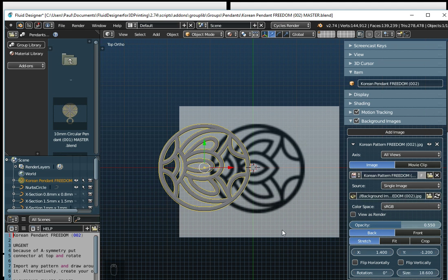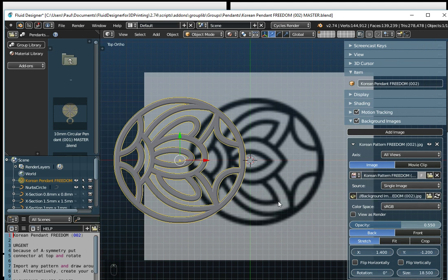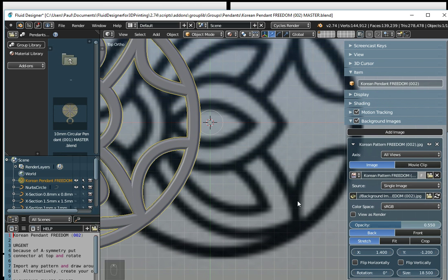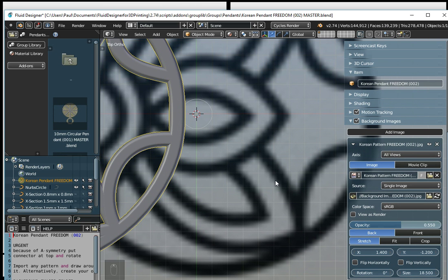And you'll have to play around with this, and essentially what I would suggest you do is select a size, put a path on here, and set the thickness to be 1:2 and see that it's okay. Alternatively, what you can do is, if you just zoom in here, you need to be looking for a thickness of this line to be approximately 1 millimeter.